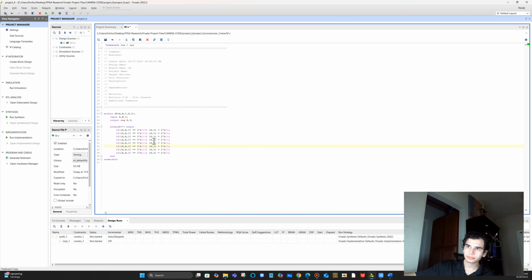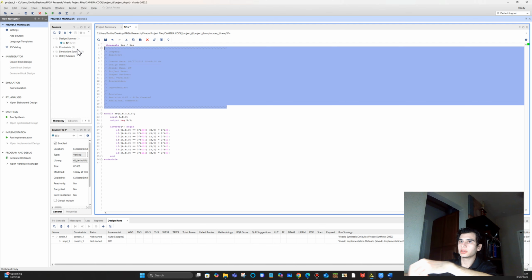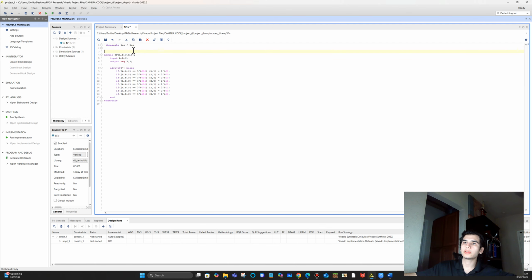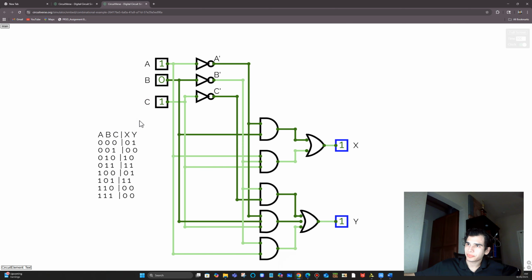Okay. So now that we have this, that's literally how you implement the entire digital circuit. You can take this Verilog file and put it on an FPGA immediately, or you can make an ASIC such that when A, B, and C are given a voltage of either 1 or 0, the output pins will reflect the exact behavior described by this table.